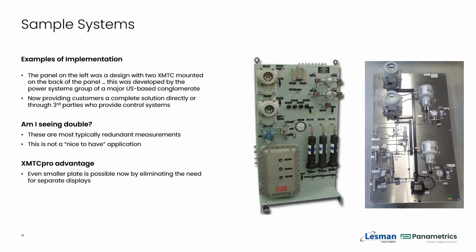Okay. And yes, that you are always going to have a redundant measurement here, folks. Regardless of whether it's SIL2 or not, they're going to have 2 transmitters per plate for redundancy purposes. It is that important in measurement.